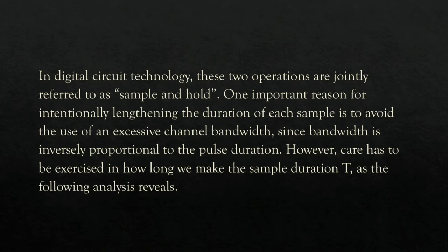One important reason for intentionally lengthening the duration of each sample is to avoid the use of an excessive channel bandwidth. Since bandwidth is inversely proportional to pulse duration, however, care has to be exercised in how long we make the sample duration T, as the following analysis reveals.